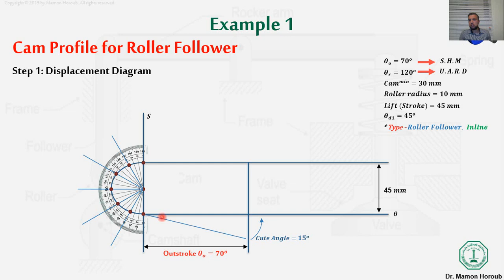But engineer-wise, because you will not have a proper number exactly, because it has multiple digits, you will not have a proper division into 6 pieces, except if you have a distance equal 60, so you will divide over 6. That means every piece will give you 10 millimeter or 10 degrees. But engineer-wise, there is a method called the acute angle, and this acute angle is always less than 20. Normally they take this acute angle as 15 degrees. So just draw a line.